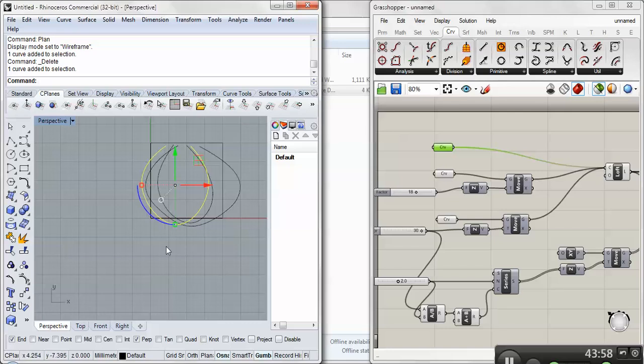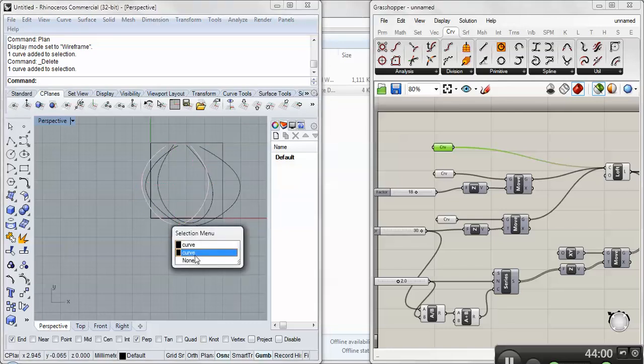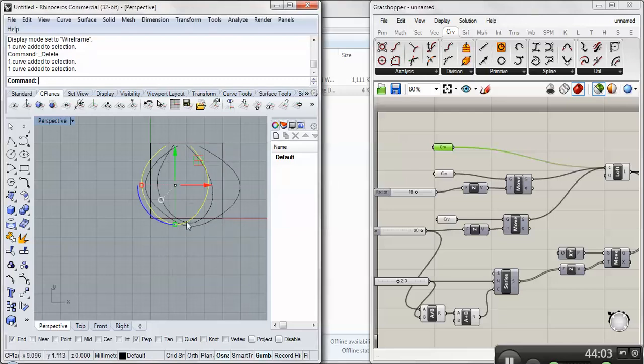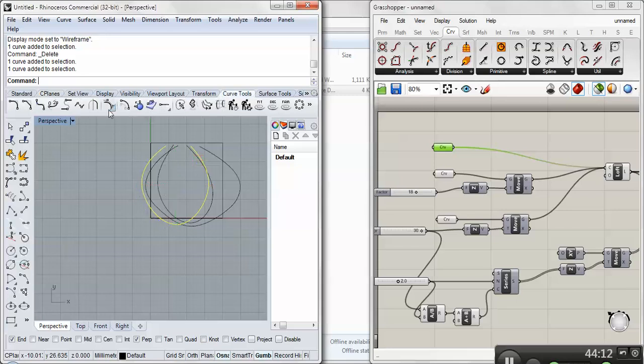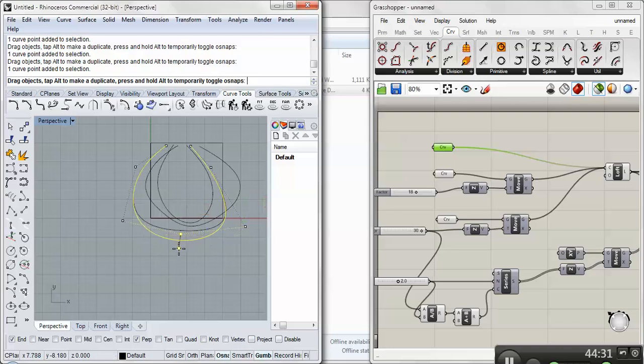because these are back in the Rhino world, not parametric, I have to adjust them manually. This is a control point curve. Even with the gumball on, I can't get to the control points that defined it. Under curve tools, we messed with this in the previous session, there is a points on, points off that turns on and gives you access to the data. So I'm going to make this guy a little bit bigger on the base, give a little more diversity to my surface.